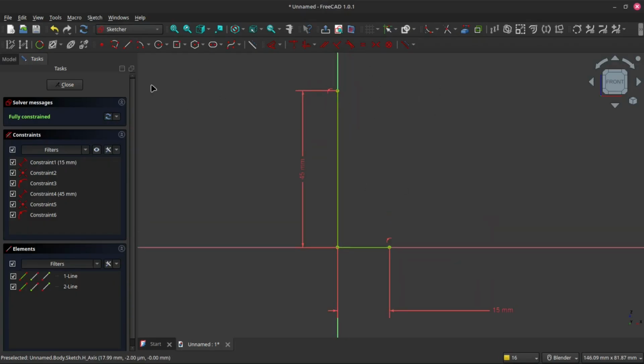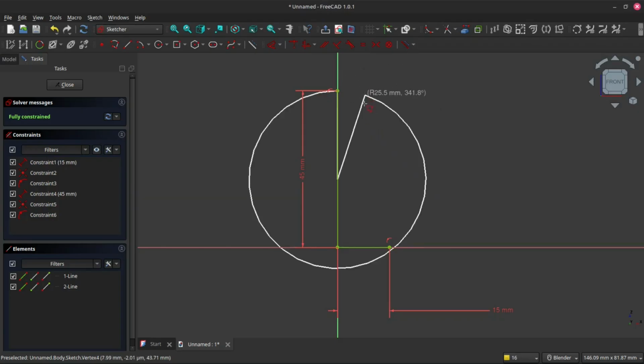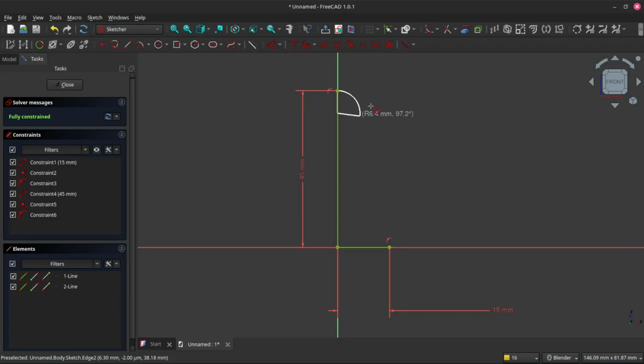And the way I'm going to do that quickly is using the polyline tool. So I'm going to start kind of at the head of the pawn. I'm going to click on this point to start. Now what's great about the polyline tool is that it has different modes, and you can switch between modes by pressing the M key on the keyboard. I'm going to find a mode that has a circular arc and that it's going in the direction that I want. There we go.